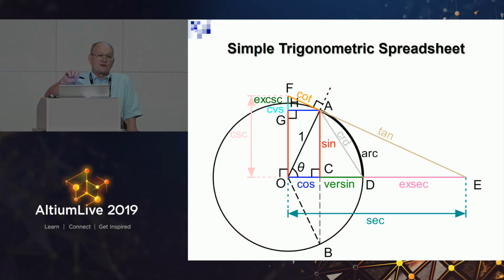and have the students write it for you, because believe me, there's really, really smart kids at the local university or the local high school that can write these spreadsheets for you, even if you can't. This is 8th or 9th grade algebra and geometry. This is not high mathematics. It's simply trigonometry. In order to figure out what should the angle be because of this size of land pattern and this size of via hole and this pitch, what should the angle be to get maximum clearance for my space? And you do it as a spreadsheet.